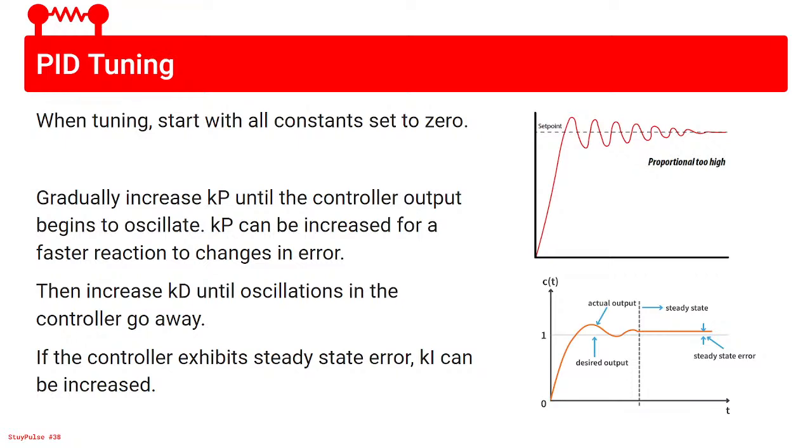Then this routine will observe the amplitude of the response, plug those into a table or a formula, and get back Kp, Ki, and Kd. This is not on the slides, but 694 has our open source code library, and we've implemented that, and you can find it there. It has worked for us, so it is something worth looking into.